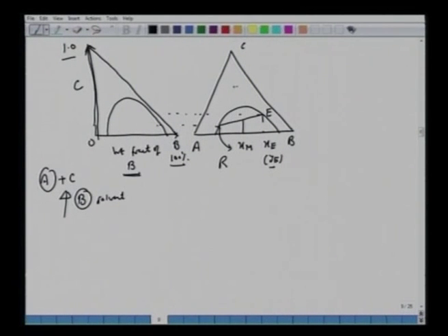Of course, here if we choose any coordinate, we can read all the 3 readings here. But the most important is what is the amount of contaminant solute you have in the system and how much solvent you are adding to remove this. So generally on the x-axis you plot weight fraction of B, and here you plot weight fraction of C, okay, and A would be 1 minus B and C anywhere. So we don't need to plot exactly on this equilateral triangle.